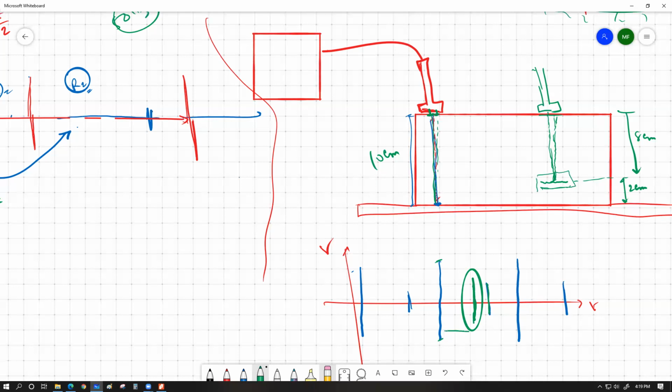And by measuring this time, we could appropriately find out where this individual crack is located. So that's also another industrial use of ultrasound for our purposes.